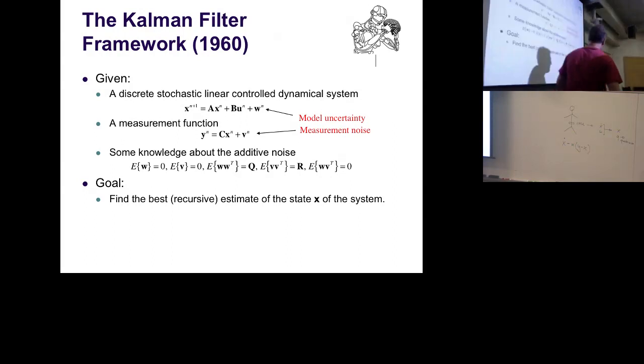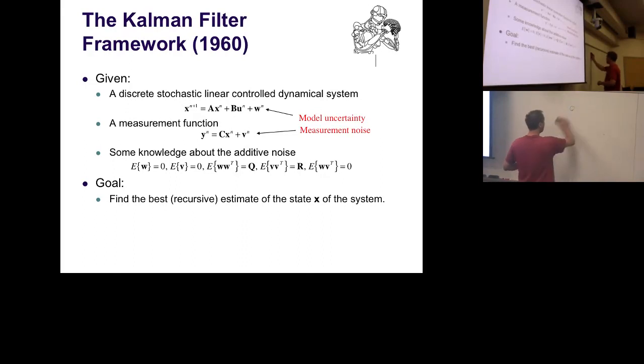We need the basic setup to get going with Kalman filtering. We take this again into a discrete time domain because it's nicer, and you will see very soon the connection to LQR control. And we take it into a linear domain, since that way it was developed. We can talk about the nonlinear extension in a similar way as we did in LQR control. It becomes essentially local linearizations at a certain point and then applying the standard linear approach.